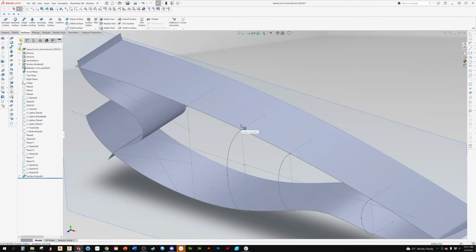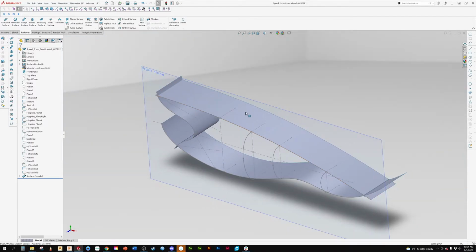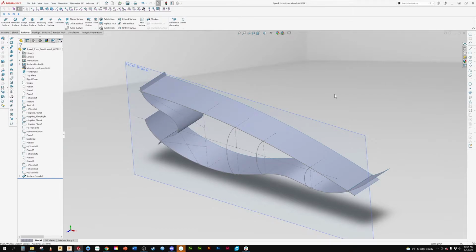And what that does, again, is it helps with having the computer understand that there's more mathematical data. So snapping to a surface provides the software with more information than just snapping to a curve, and that more information allows you to get better surfaces and also ensure that there are no little missed glitches.